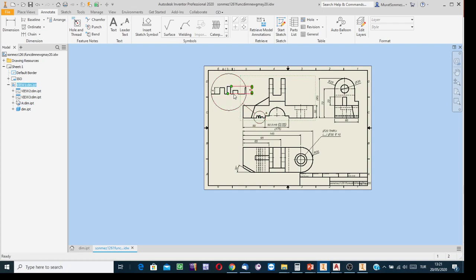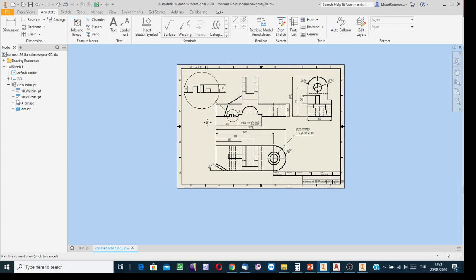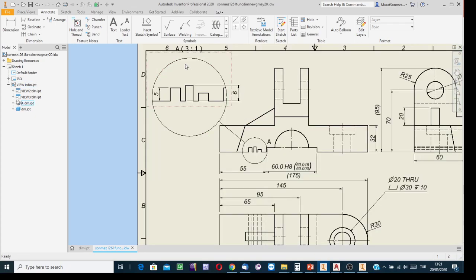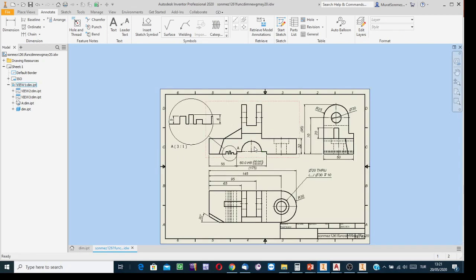If it is still impossible to prevent the clash, then this means you need to use a greater size paper or decrease the scale factor. I'm going to take this note from the margin and bring it to the vicinity. It is going to be more distinguishable. Region A, detail view A.